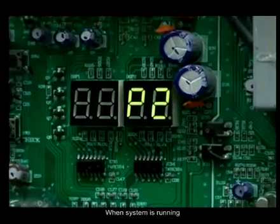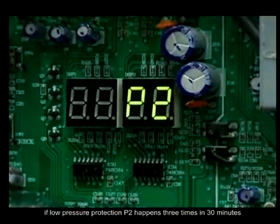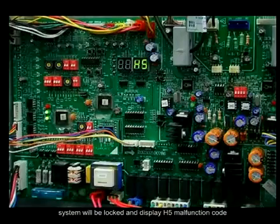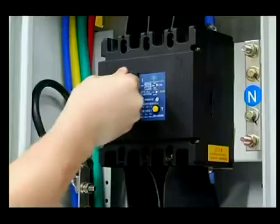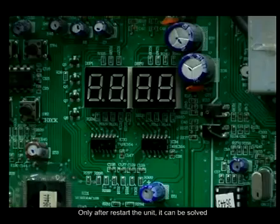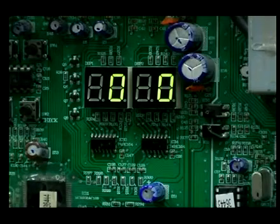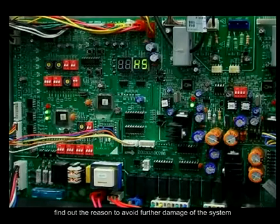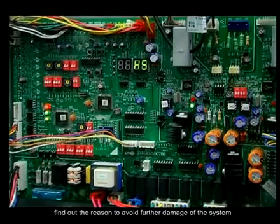When the system is running, if low pressure protection P2 happens 3 times in 30 minutes, system will be locked and display H5 malfunction code. Only after restart the unit can it be solved. At this moment, you should check and repair the system. Find out the reason to avoid further damage of the system.